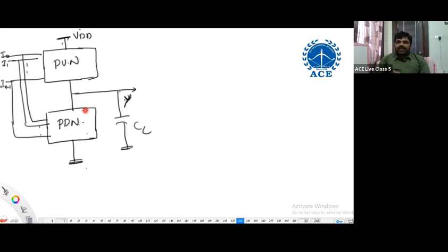After writing the dual, complementing each literal gives the complement of a function. While constructing using switches, you are using the dual nature in construction. What do you mean by this? Switches in series are replaced with parallel, and switches in parallel are replaced with series. So dual in nature in construction, and on and off conditions are complementary, because we are using two complementary MOSFETs.